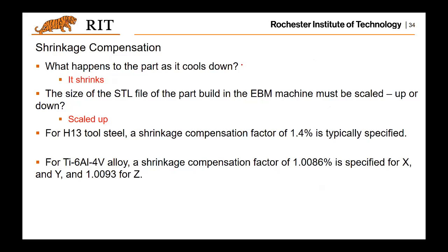So you want to scale up what you designed before you use the EBM printer to print the part. And there's some heuristic. It's material dependent, right? Different materials have different shrinkage factors, and the compensation factor will also be different.